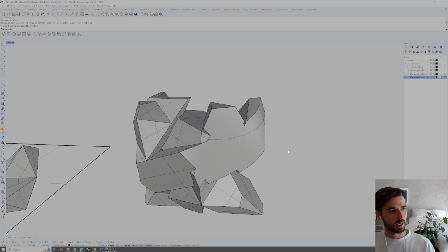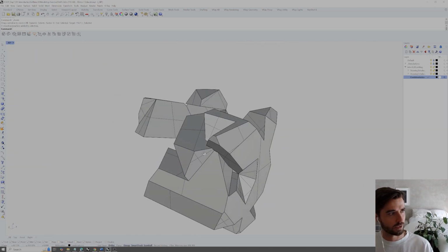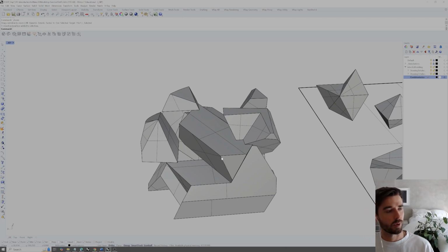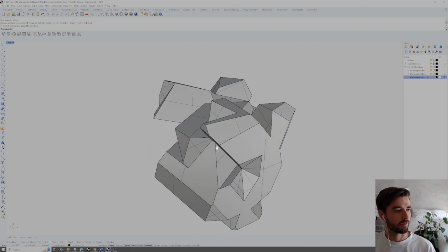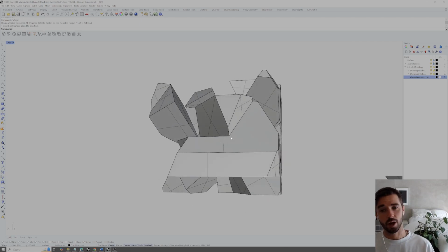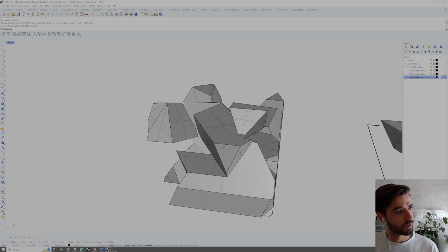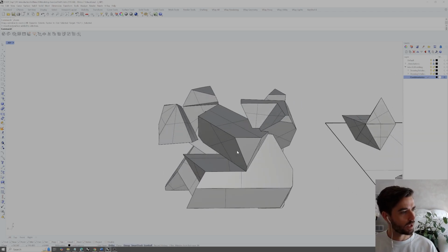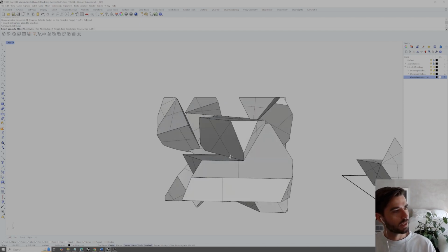And this is a good step to go through with any Boolean operation, because they tend to make quite messy geometries. And generally when we're designing or developing something inside of Rhino, we have quite precise measurements or curves that we're working with. So this is going to be a way of thinking about that curve precision and surface rebuilding by showing you a couple of ways to rebuild a messy polysurface. So the first thing I'm going to do is go in and fillet certain surfaces using the Fillet Edge command.